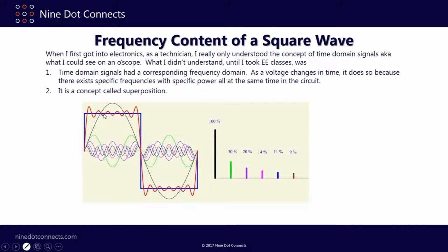So you're going to have the fundamental of that square wave. That's what you see here, and the black is 100%. Then you also have the odd harmonics. So this would be third harmonic, fifth harmonic, and so forth and so on, in these relative weightings of the signal strength. And you can see here's the third harmonic, so here's 3 waves all within the same base period.